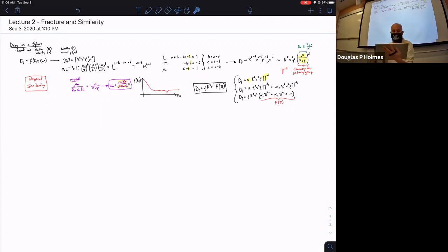So for instance, in this problem, as long as your goal is to keep pi the same, you might be interested in figuring out how f depends on pi as you make the radius of your sphere bigger, and you might not be able to make an experimental setup that allows you to test a radius so big. So you keep this pi parameter, the ratio here, the same, and that'll tell you what's going to happen as you scale up or down the radius of your sphere.